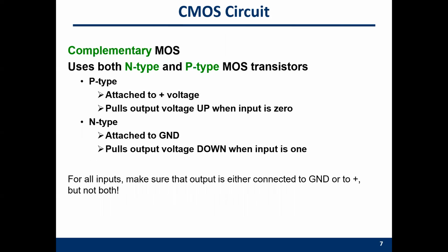So by two types of CMOS transistor, we can build a network. And this network can implement some functions like AND, OR, NOT. And this network actually consists of two components. One is a so-called pull-down network, which is connected to the zero, to the ground. So we use NMOS. The other one is a pull-up network. It's connected to the VDD, so we use PMOS.